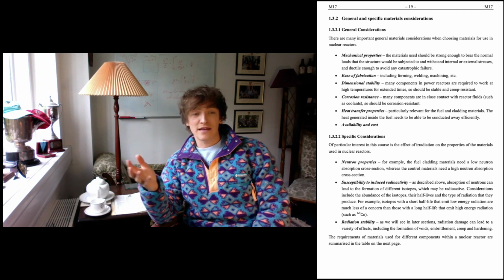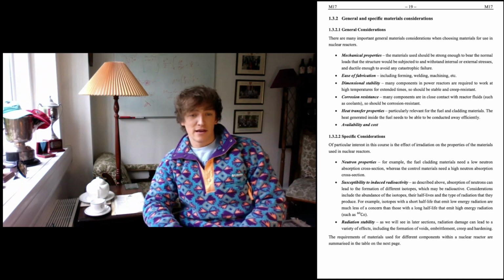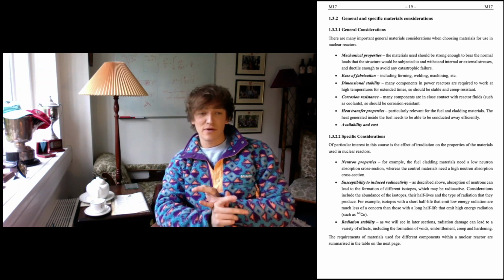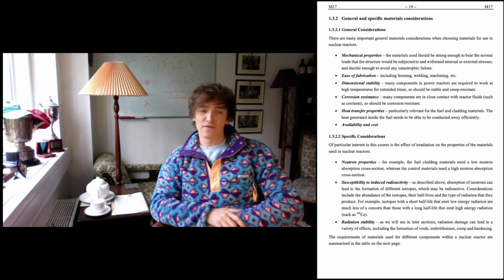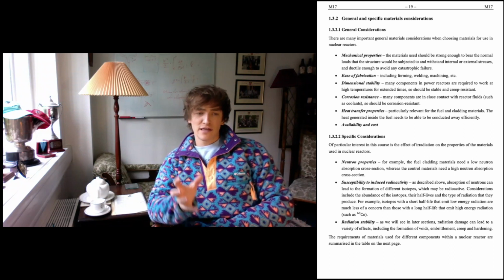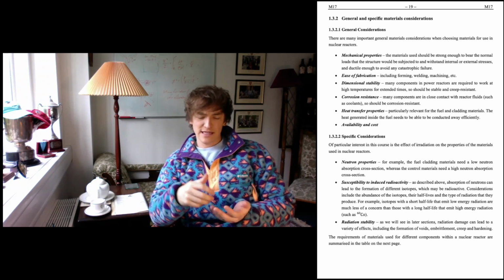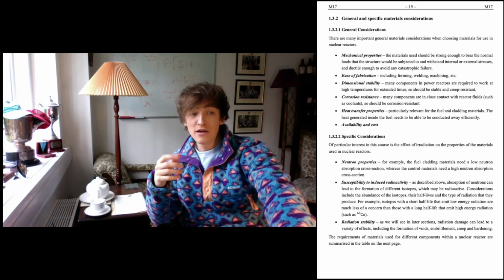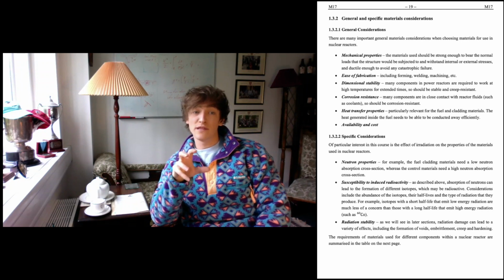Radiation leads to many weird and wonderful phenomena, including the formation of voids, catastrophic embrittlement, and radiation-induced creep. Radiation-induced creep is creep at temperatures where you would not normally expect creep to occur, but it occurs because of that radiation. And they're the sort of considerations that must be covered when choosing a material for application in a nuclear reactor. Throughout the rest of this course, I'm going to look at those key components and how such concerns play a part in deciding what materials are chosen.